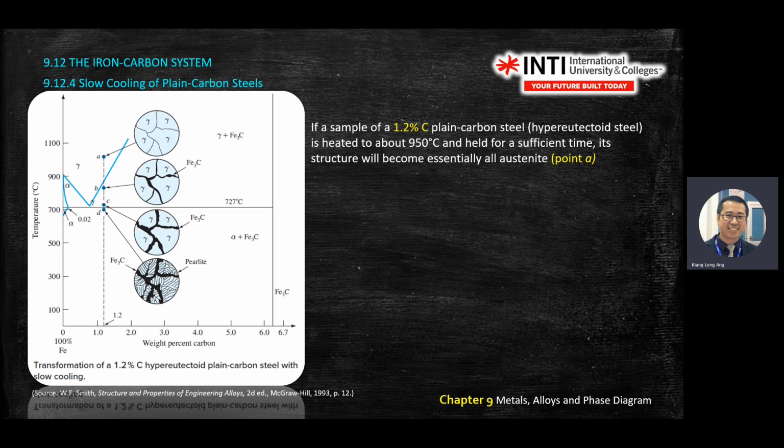So here it passed through, and then you look at the phase diagram. Here you have Fe3C. So you go to the boundaries between the gamma, you fit in the Fe3C. Then you drop down, you pass through the pearlite eutectoid, and then pearlite starts to form.